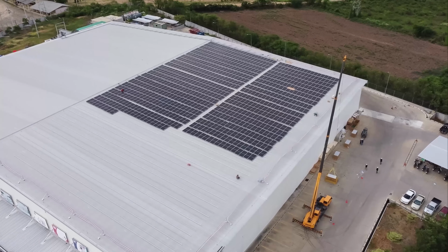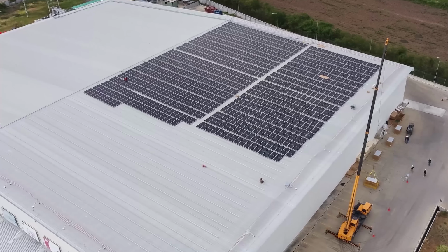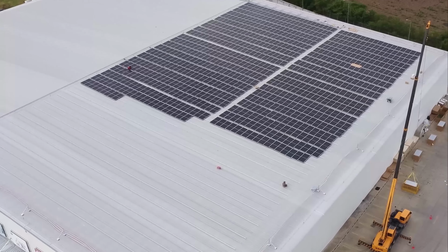If you've got a site which has a decent-sized, unshaded, south-facing sloping roof, and you'll use a large proportion of the electricity you could generate within your own site, you could expect to get a payback time of around 7 to 10 years from solar PV. And that's not bad, because you can expect the system to work reliably for 25 years or so with minimal maintenance. I hope you found this useful.